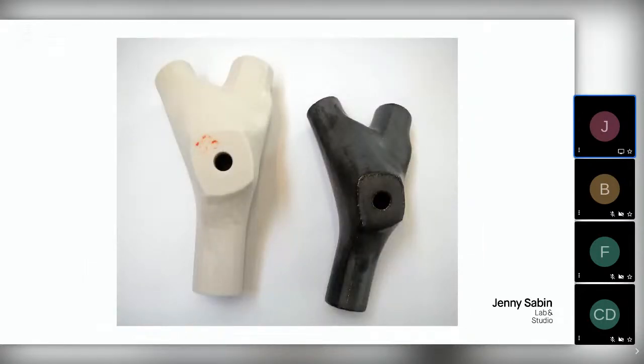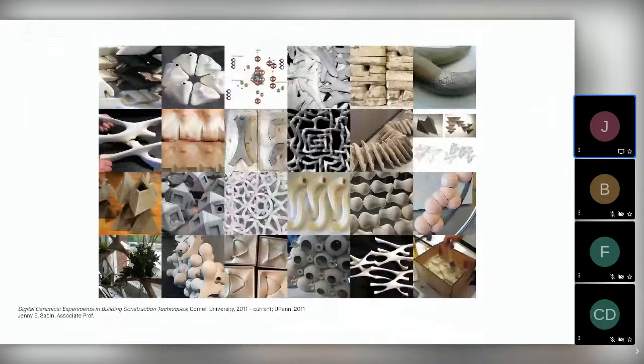that we could directly print ceramic componentry. And so here you can see the same part printed on the left with the proprietary media, and on the right printed in my clay recipe, bisque fired, so chemically changed to ceramic, and then glaze fired to achieve the final part.